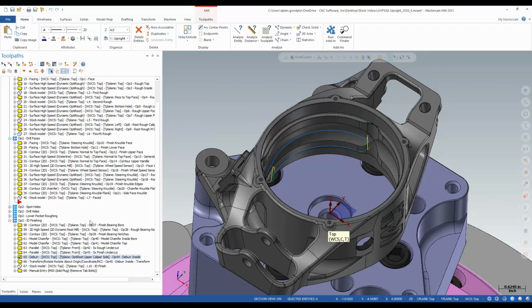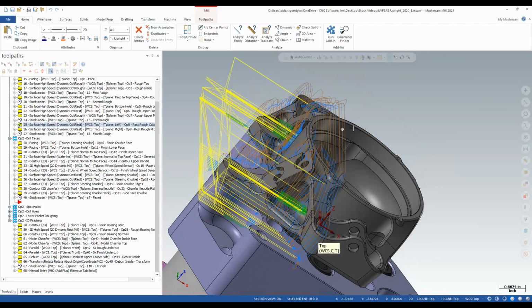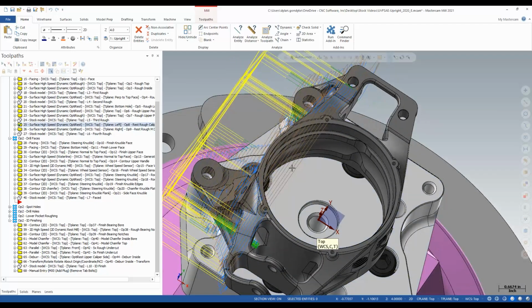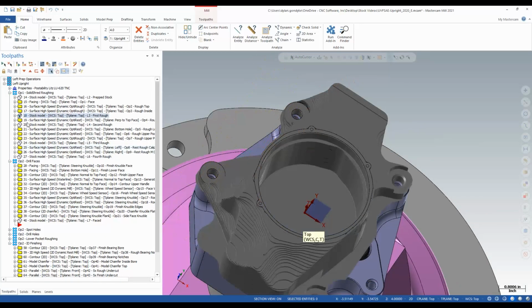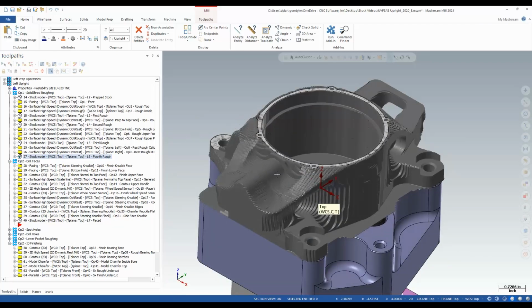We don't need to generate a stock model that shows what those operations do, because the end goal of creating these stock models is to leverage them to create efficient machining motion, cut down on air cuts, intelligently stay in the cut and remove only the material that's left. So we pick and choose when we want to create these stock models to leverage them to make our program smarter. And that's the real power of using these models in process.